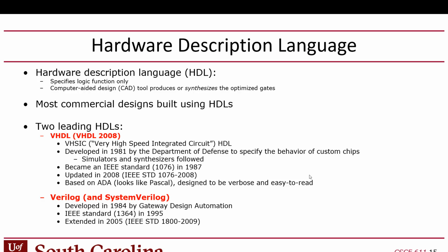for it, like a simulator, where you take the VHDL code and you could actually simulate it, and then after that, they came out with these tools for synthesis, where you could take the code and automatically generate gates and wires from that code, like you could use it to compile the code into hardware, right? But that was never the original intent. I don't believe so anyway. I think the original intent was just to use it as a way to concisely describe the behavior of hardware.